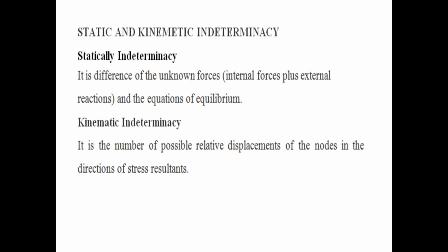And finally, static and kinematic indeterminacy. Static indeterminacy is the difference between the unknown forces, that is internal forces plus external reactions, and the equations of equilibrium. And next, kinematic indeterminacy is the number of possible relative displacements of the nodes in the direction of stress resultants.